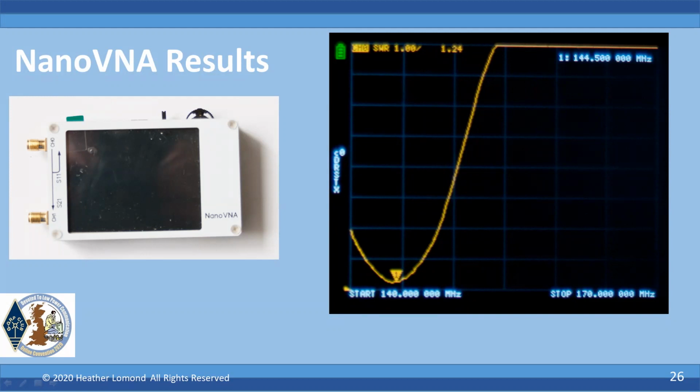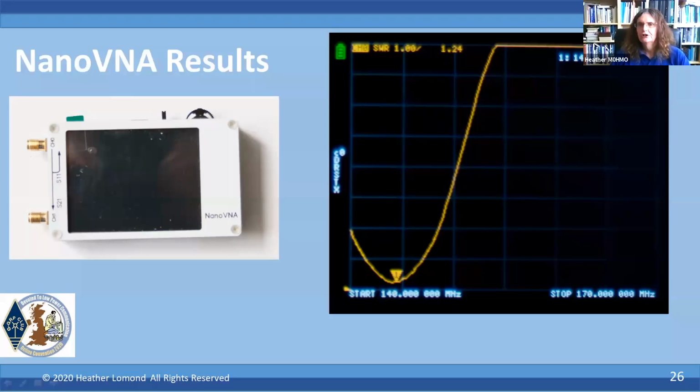Okay. We've covered calibration, port savers. Have you tried to do a polar diagram with a VNA? A polar diagram, yeah, well, you can do it. I think the NanoVNA software does include that kind of thing, certainly the PC side. And of course, you've got the Smith chart, which will give you some form of that in terms of the angle and the magnitude of the signal.